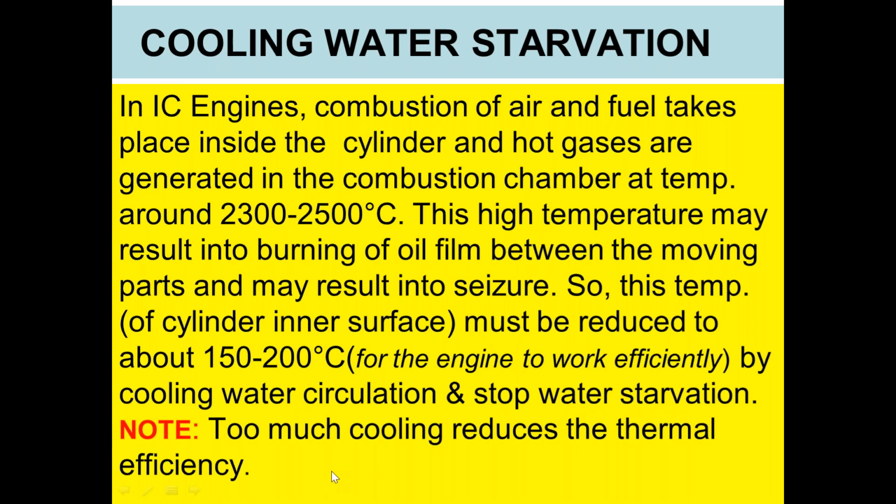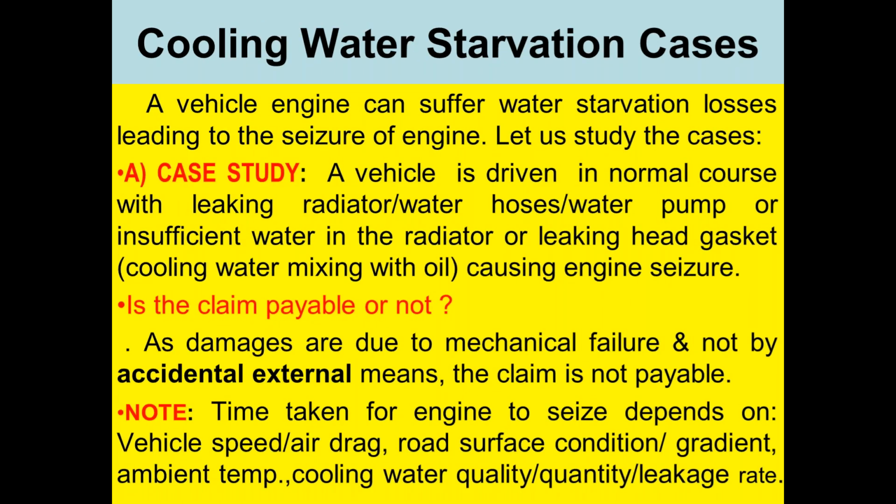Too much cooling reduces the thermal efficiency. Cooling water starvation cases. A vehicle engine can suffer water starvation losses leading to seizure of the engine. Let us study the cases. One case: a vehicle is driven in the normal course with a leaking radiator, water hoses, water pump, or insufficient water in the radiator, or a leaking head gasket, with cooling water mixing with oil and causing engine seizure.